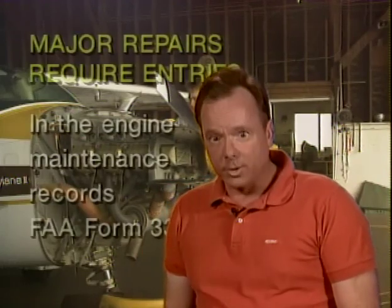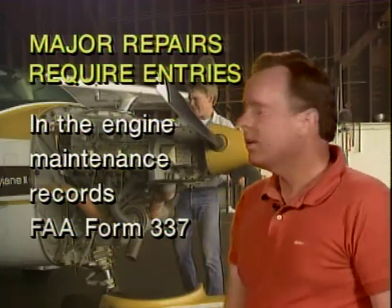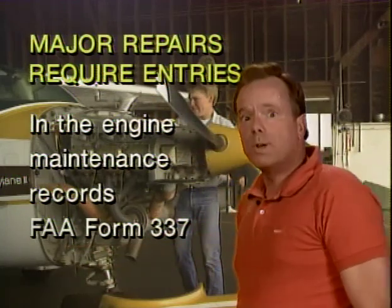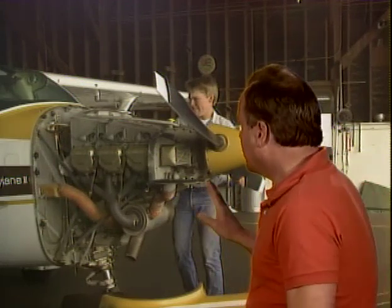All right, now let's assume you do make a major repair on an aircraft engine. Where would you make entries? Well, you'd make entries in the aircraft maintenance records, but you would also fill out a Form 337. When do you have to fill out an FAA Form 337? Anytime you make a major repair or alteration. What's a major repair? Well, a major repair is one that, if it's not done properly, might affect the way the airplane flies, might affect its strength or performance, and therefore it's a major repair, and you'd have to fill out that Form 337.